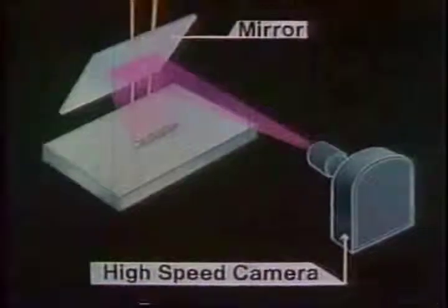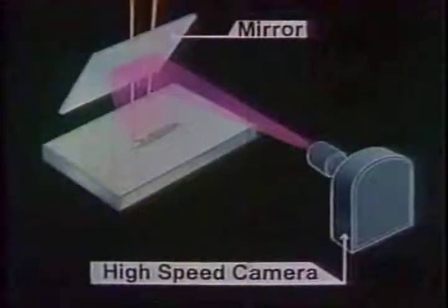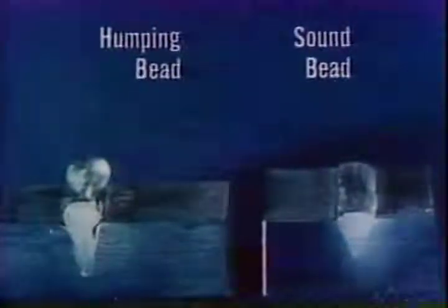Let's observe the actual welding of thin plate by tandem electron beam using the method shown here. This is what happens when only a single beam is used. The humping phenomena is clearly seen. Next, let's impinge the second beam on a suitable area of molten pool. Humping phenomenon disappears completely. This is due to the effects of the second beam in controlling the metal flow in a pool that results in remelting and filling up the solidified wall produced by the first beam. Thus, a sound weld is obtained by the tandem electron beam process.